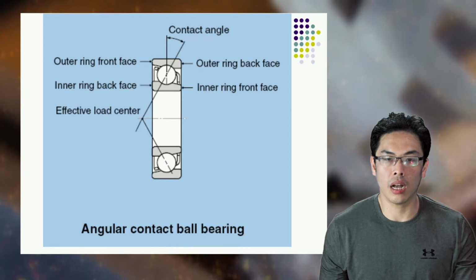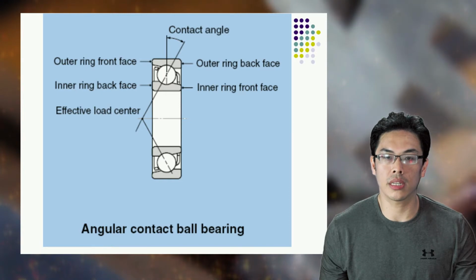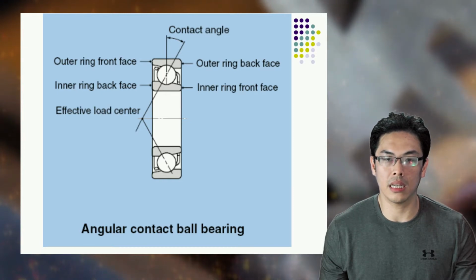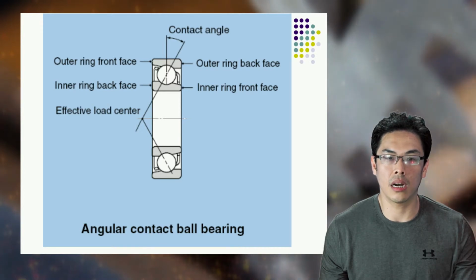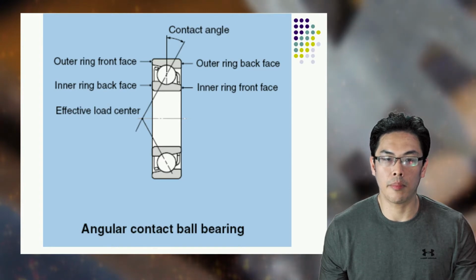An angular contact ball bearing uses axially asymmetric races. An axial load passes in a straight line through the bearing, whereas a radial load takes an oblique path that tends to want to separate the races axially.